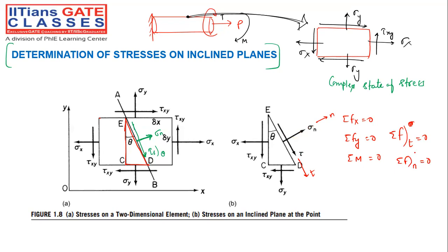By using this engineering mechanics concept, you can develop the formula for the stress value at an angle on a plane which is defined at an angle theta from the vertical, right? So we are having the sigma theta and tau theta. How can we find them? That's very simple. You should just know the fundamentals of engineering mechanics. You can prove it very easily, right? Remember, summation of forces has to be equated to 0, not summation of stresses.